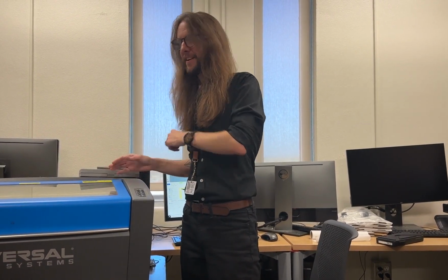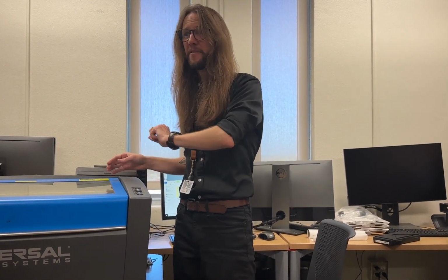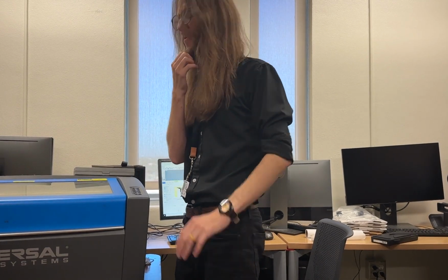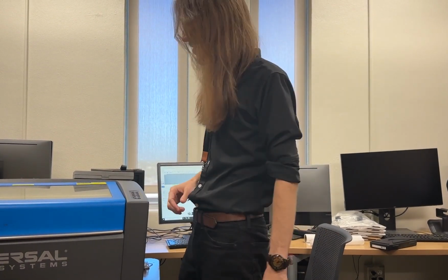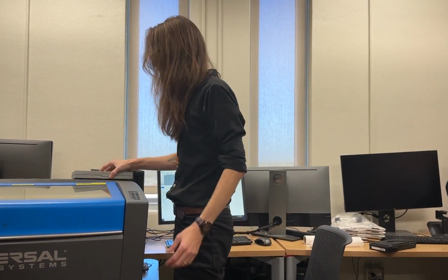You never just leave a laser cutter, especially if you're doing something that's going to take 4 hours. You need to sit there and watch it for 4 hours. So don't go rastering stuff, which is good. We don't even use rastering in architecture very much. For the most part, you're probably going to be cutting and scoring items.